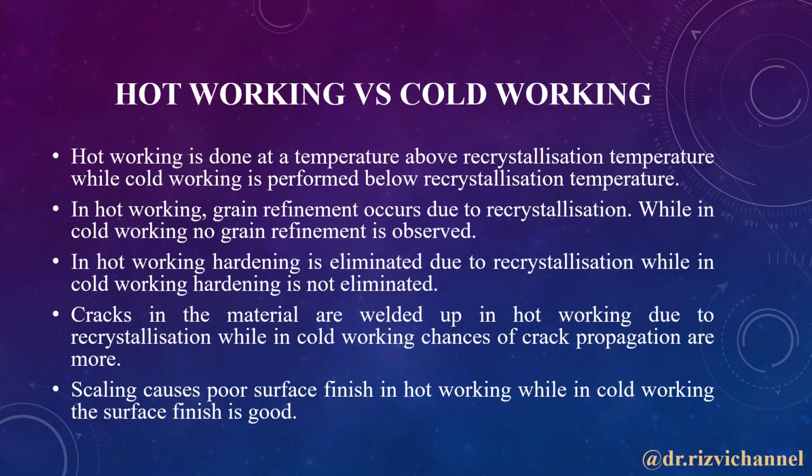Finally, scaling is observed when we are working above recrystallization temperature. This scaling is due to oxidization of the upper layer of the material and it causes poor surface finish in hot working. But in cold working, no scaling is there, so the surface finish obtained is good.